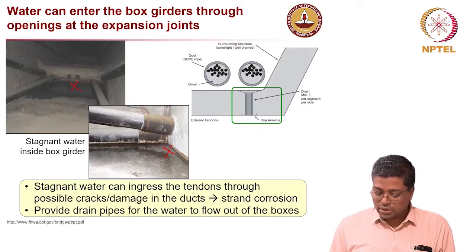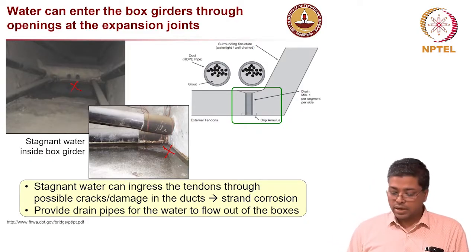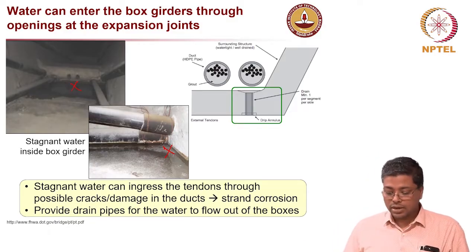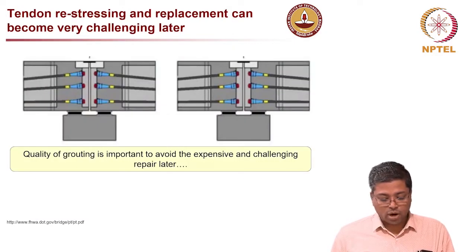There is a design procedure where they suggest providing a drain hole on the segment for draining the water. Whatever possible water stagnation there is, it will drain and let the water out. It's very important to keep these systems away from water.